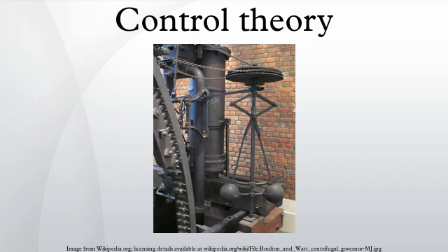In a closed-loop control system, a sensor monitors the system output and feeds the data to a controller which adjusts the control as necessary to maintain the desired system output. Now, when the car goes uphill, the decrease in speed is measured, and the throttle position changed to increase engine power, speeding up the vehicle. Feedback from measuring the car's speed has allowed the controller to dynamically compensate for changes to the car's speed. It is from this feedback that the paradigm of the control loop arises. The control affects the system output, which in turn is measured and looped back to alter the control.